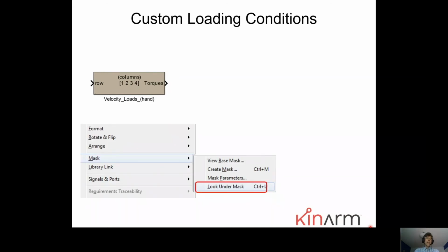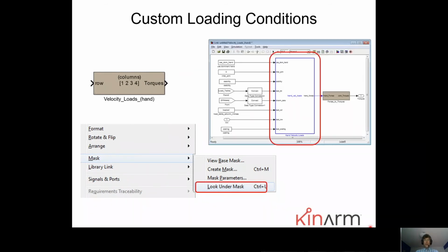If you right-click on any of our blocks, go to select mask, and then look under the mask, what you'll see is the code that we have implemented to create that block. So that's what's shown here. In most cases, there are a number of inputs and outputs that are all feeding into and out of some sort of embedded MATLAB block, and that's what's been highlighted in the middle here.